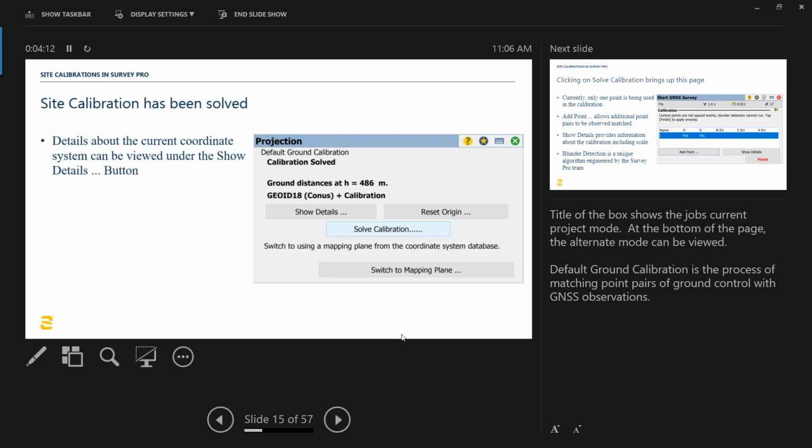So the next comment and question was, I always thought that 2 point vertical calibrations were bad. Is that wrong? Well, yes and no, right? So again, think about what a vertical calibration is correcting for. A vertical calibration is correcting for two physical effects.